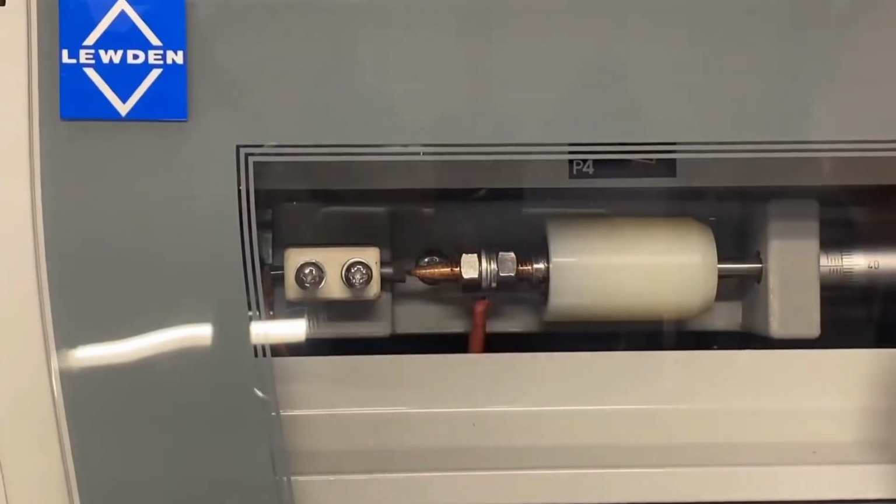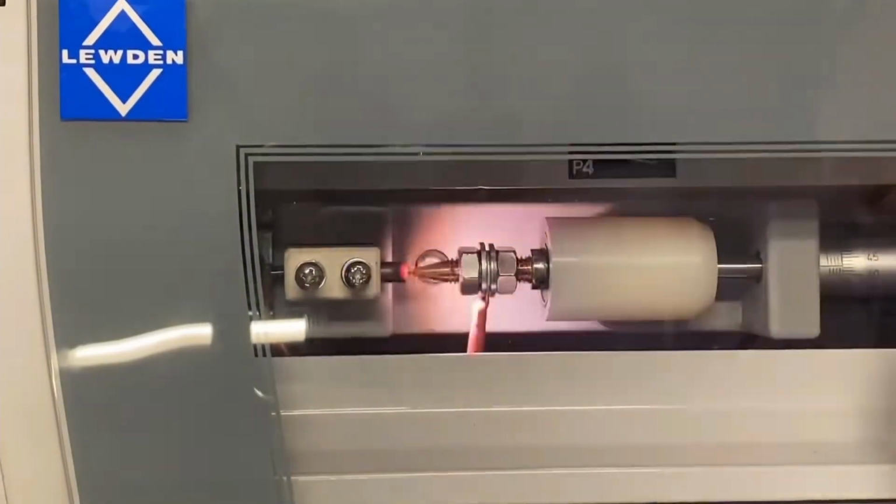However, there is one more kind of fault that has become increasingly common, and that is the arc fault. These are generally caused when connections work loose over time and the connection between the conductors becomes tenuous. If the current flowing into the circuit is high enough, it can jump this small gap in the form of an arc.